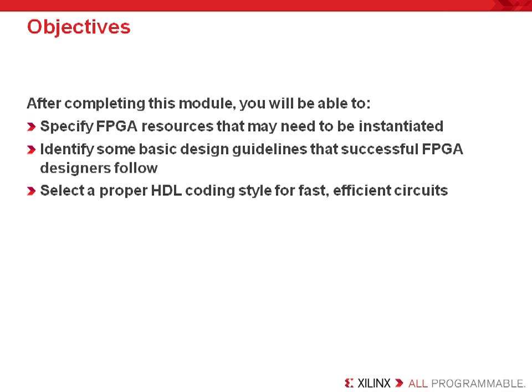For example, the block RAM resources are inferable for memories that only use a single block RAM, are not initialized, and don't use the output register functionality. So simply put, it is too difficult for synthesis vendors to keep up with all the possible configurations of a single FPGA resource and build the ability for the users to infer all that possible functionality. So in the end, since most customers want the high-end resources, the newest resources, and all the functionality, that requires them to instantiate. To aid customers in building a desired component of complete functionality, we recommend that users build their components with a core generator or architecture wizard.